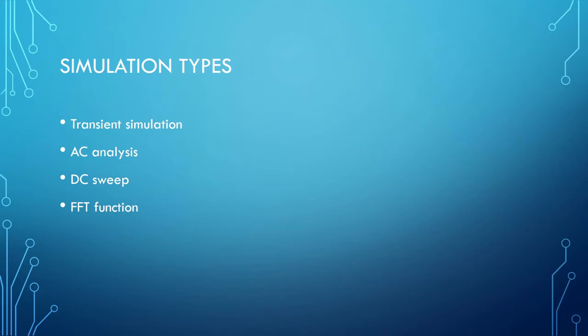The transient simulation is time-based. AC analysis is for our frequency responses. DC sweeps is for input versus output. And FFT is to see harmonics in our system.